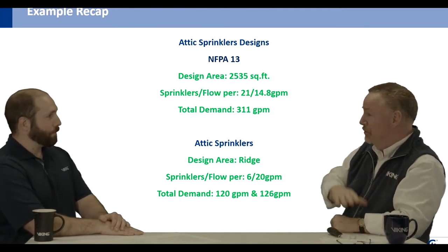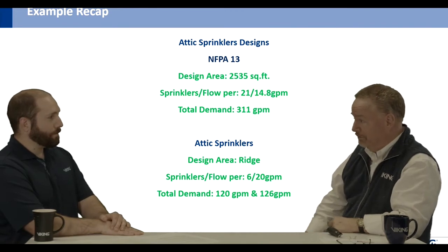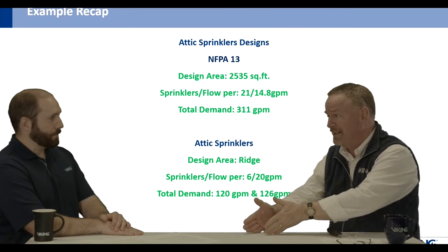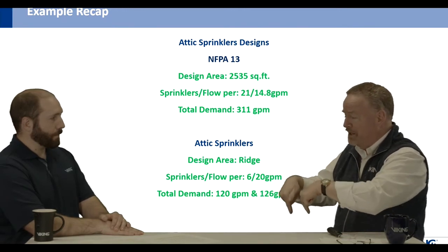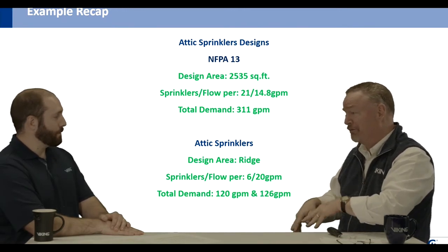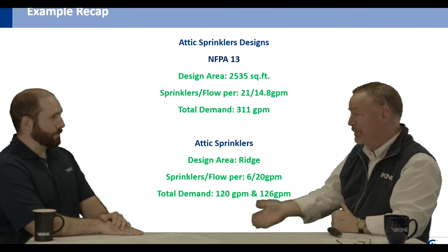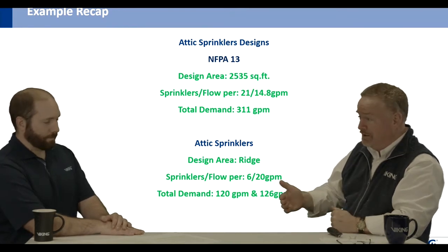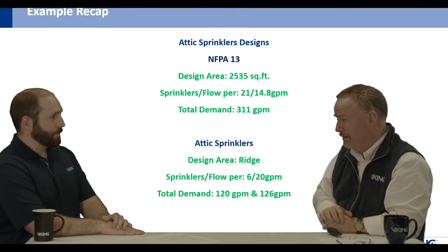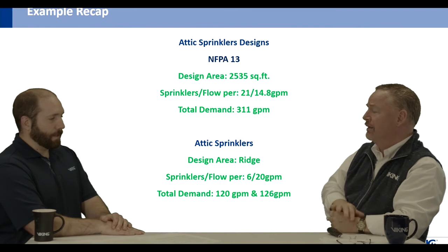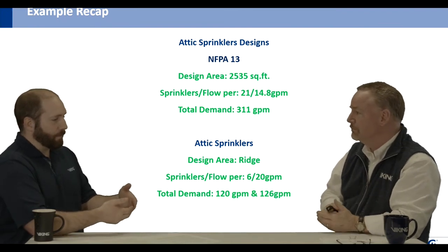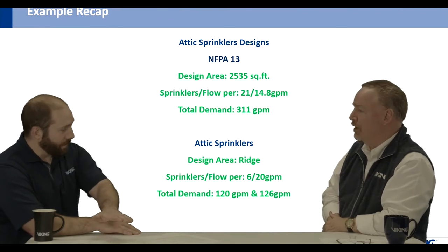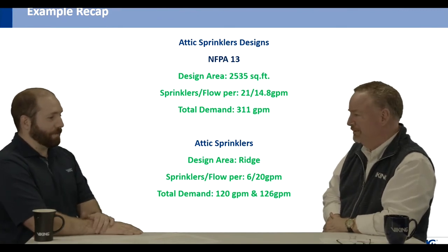So no, you can't use it down to the floor, because you have to remember, when we're protecting churches and gymnasiums and things like that, it's all about what's on the floor that's burning, and you have to be able to deliver that kind of density down there. Correct. Not to say that we couldn't do it, it's just not been explored like that. Right. They're specific applications for a reason, where we're trying to put a fire out in an attic, not necessarily trying to provide the proper area density coverage for the floor space below.